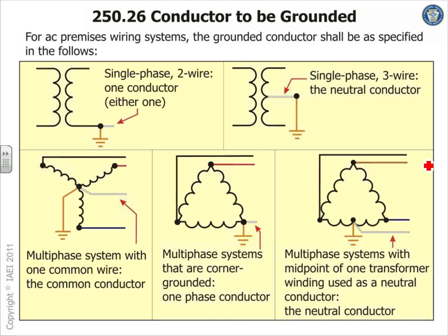Here's a couple of systems, guys, that we use that's grounded. A lot of people, guys, take an ungrounded system and they ground it to stabilize it. What's the disadvantage of using a corner grounded system? If this was a 480 system, now your voltage to ground is 480 at all times. So that's the major disadvantage. What's the advantage of it? It stabilizes the voltage to the ground for you, and it eliminates the over voltage problems that it creates in your system.